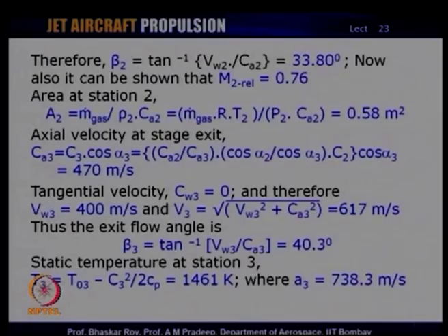So, both the entry and the exit velocity from the rotor are deliberately kept subsonic to avoid shock losses, which again would increase the losses and reduce the efficiency of the turbine. And most of the present day designers are extremely sensitive to the efficiency of the turbines, and hence they try to keep the turbines subsonic even today.